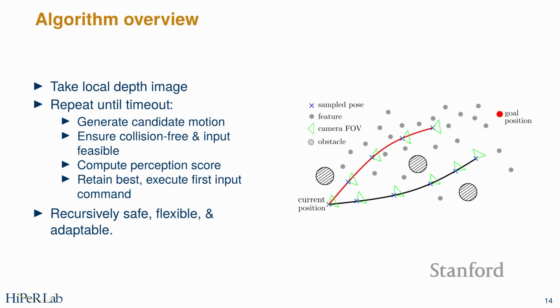It is then a necessary condition that your motion plan as the sphere does not collide with anything in this assumed perfect depth map of the world. Then the trade-off that you make is speed towards the goal, so how much progress do I make versus the uncertainty that you accumulate as you move. But for both of those, collision-free is a necessary condition before you'd even consider the cost.